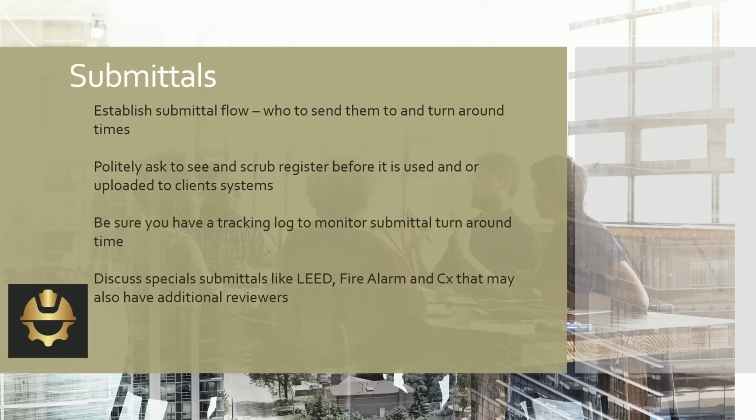If you get going on a project and your submittals are holding up, they're going to come down on you as the QC manager, and they're going to be up your skirt, and they're going to be breathing fire. So you've got to be able to show that you didn't leave stuff sit on your desk and that you processed it timely, you got it to this person, they're not doing it within the set amount of review time. That's the kind of ammo that your site team needs so that they can stay on them. In a perfect world, all the entities abide by their review time and nothing gets held up and it flows awesome, but that very seldom happens.